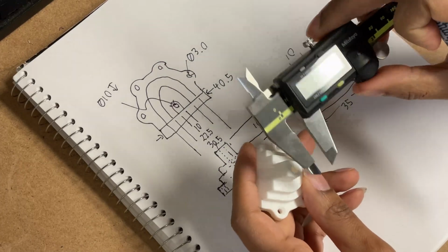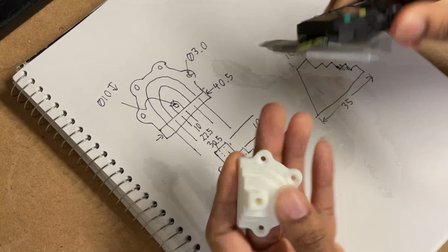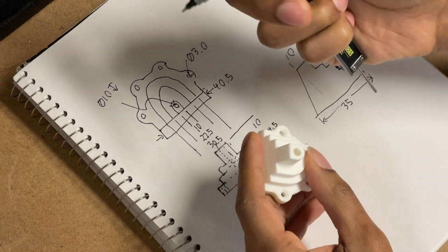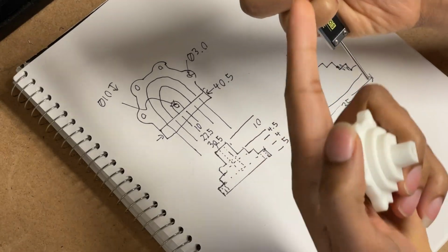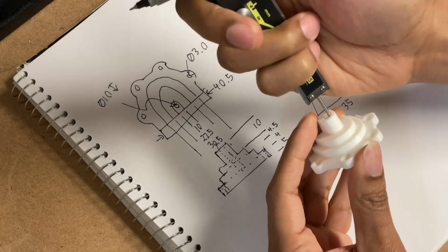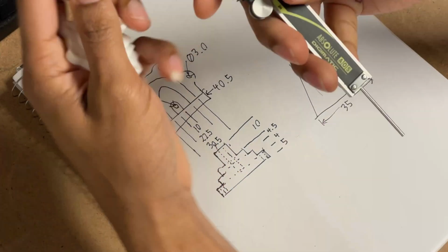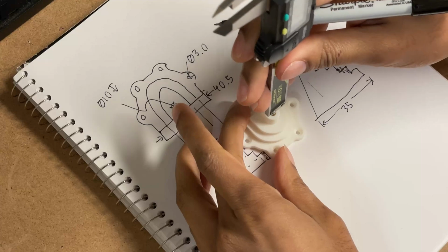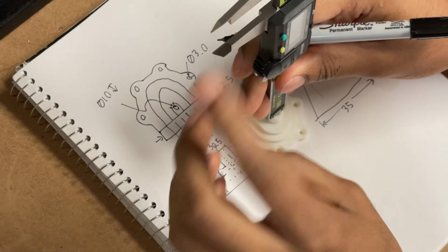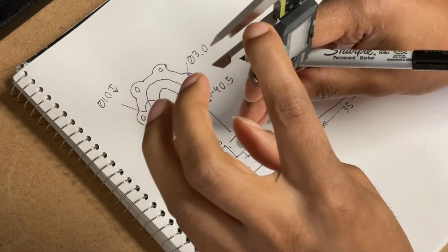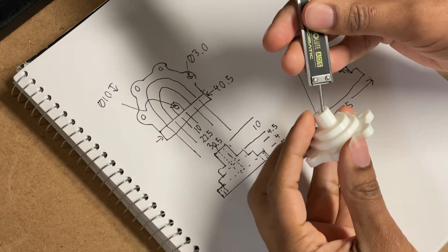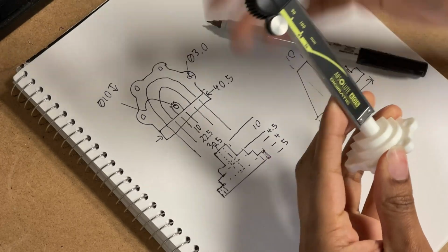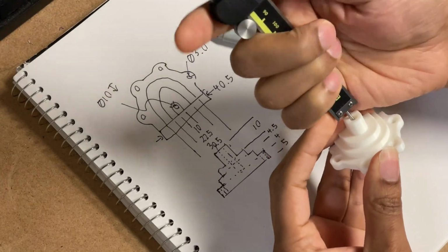Well, we can't use these jaws or even the step to measure depth. But the fourth way of measuring with a caliper, was I calling this a micrometer? This is a caliper. Fourth way of measuring is using this at the back here. See how that comes out? And we can measure depth like this. Watch. Boom. Now the key here is making sure that when you take this measure, you're sitting square and flush and flat at the bottom. So let's see what we get here.